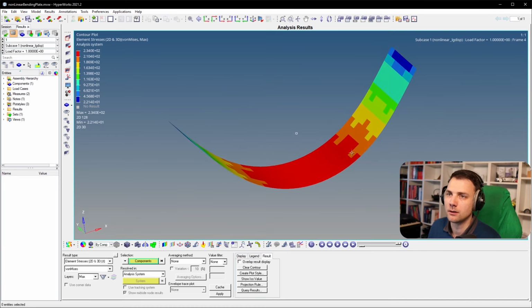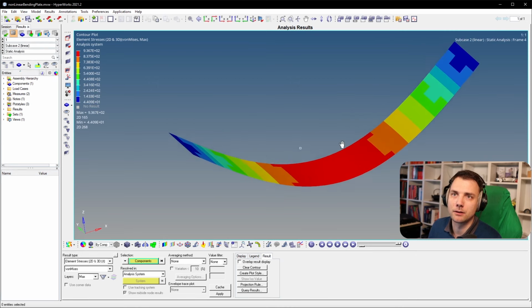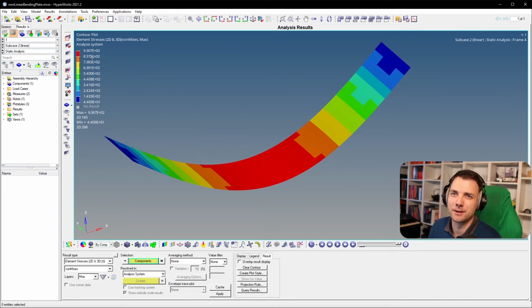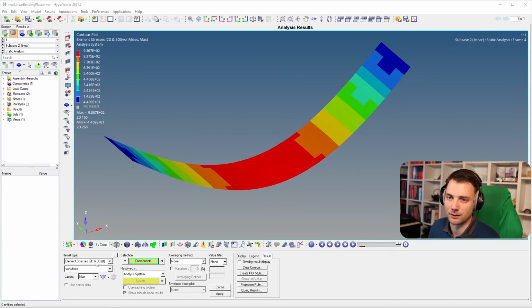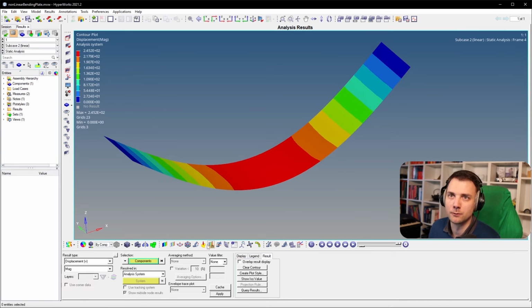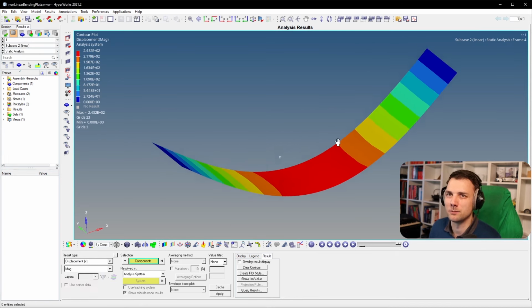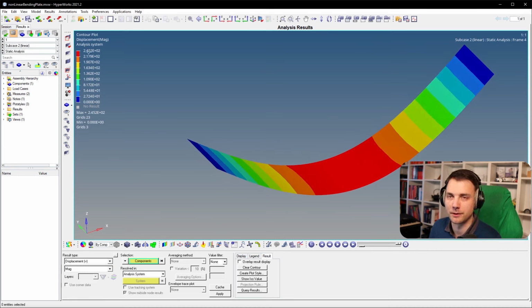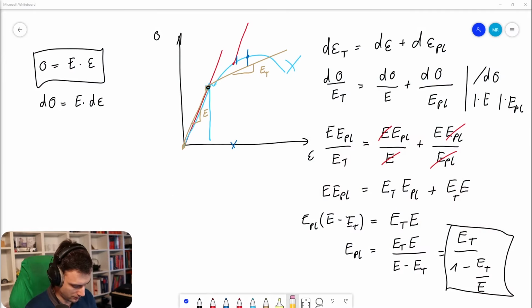234. And now let's compare that to the linear model. For the linear model, you have this 936 megapascal and far less displacement, I would guess. 24. It's not that much less, but it's less displacement but higher stresses, and that's the case here because, as I showed you here, in the linear model you're up here, and with the nonlinear model you're ending up on a lower value, but with larger deformations because you would have less stress, larger strains.